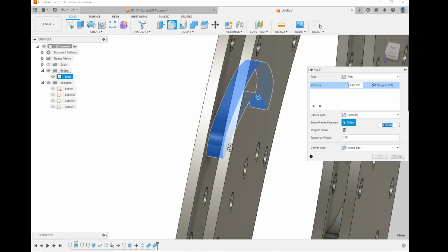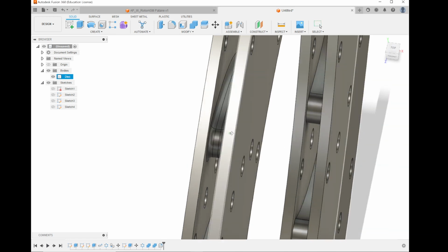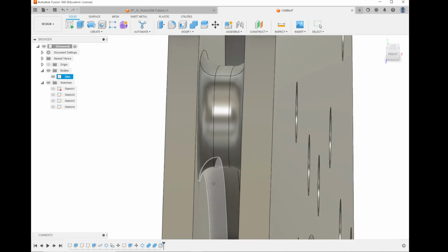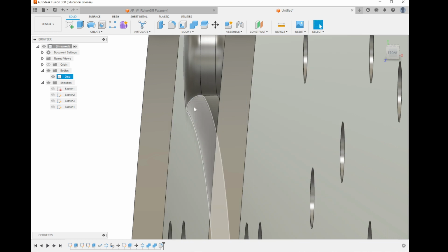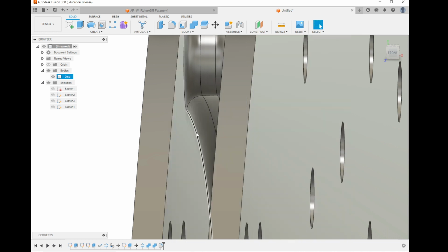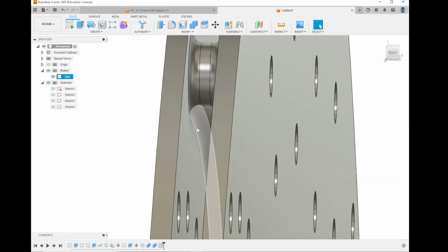So over here, I highlighted this whole thing with the filleting tool, and I can change this filleting. Let's say we want 0.5 millimeters in the filleting tool, or we can go even larger for the sake of the video. We can press 1, and if I press OK on this filleting tool, look at what happened to this thing. See how this part over here did a curved line throughout it? So this looks more like a realistic part that's being cut by a machine.